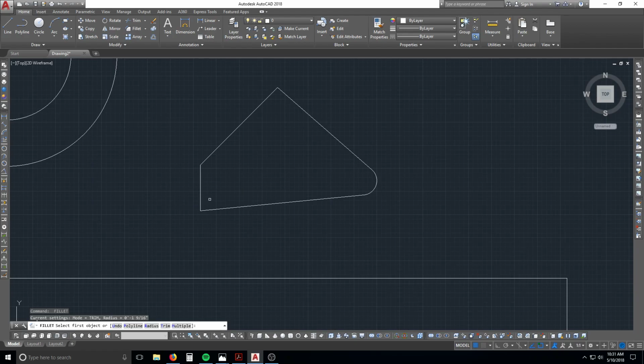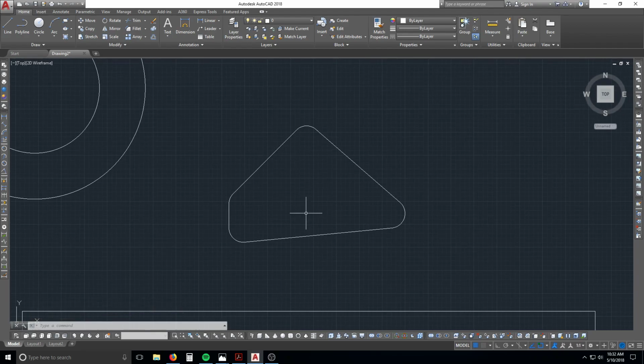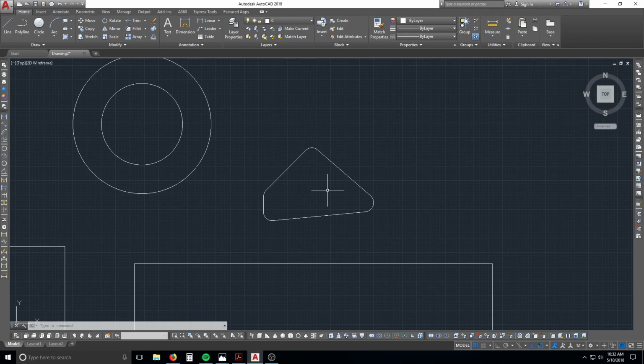You can do it again, because it remembers fillet, and it's also going to remember the radius you've previously established. So you left click. If you wanted, you can keep doing it. There, enter. There you go. That is a powerful one, one of the ones that I use a lot, because it's like a double command. It trims and connects your lines, and it can create an arc for you. That's one that really helps speed you up. Alright, so that one was good.